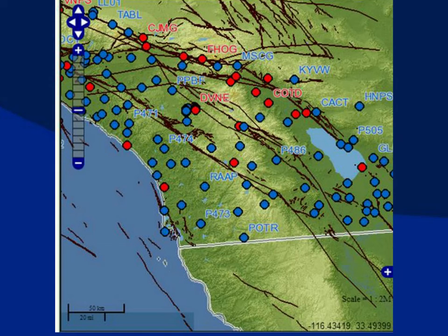In this particular slide, the California reference network, these are all individual RTK bases. They're not talking to each other. So it's up to you as a user to find the closest one to you. And again, all I did down in San Diego was bring up this map, find the closest RTK base to me, and then I could pick the mount point. It was P475. That was the name of the station, and that's the one I used.